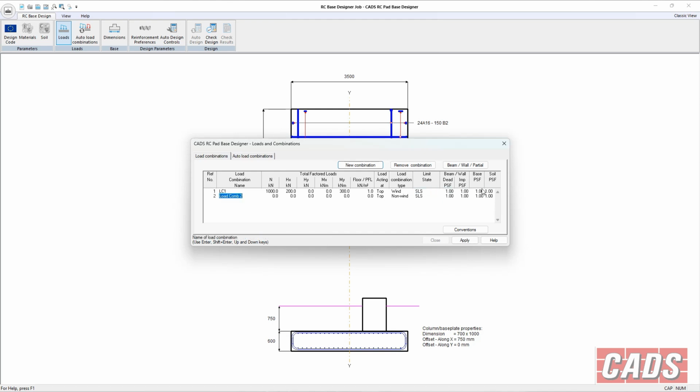Once we've done one, let's put in another load combination. This will be our ULS case. So let's have a bit higher values here now, because these are factored loads, remember. 300, 0, 0, make this 400. And again, a bit of a floor load coming in. We've got a wind contribution in there. And this is ultimate limit state. Now you can have stability or just straightforward design sets as we've got there.